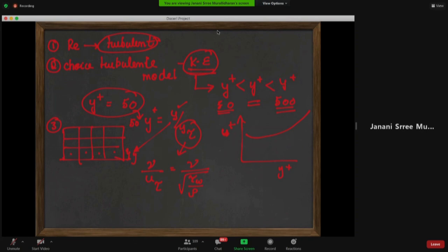This is still pen and paper work, and you need a tau wall. So you're going to go into literature for a generic tau wall empirical expression, which will be some function of Re, some numbers like 4.65 Re to the power 0.8, something like this. Okay.